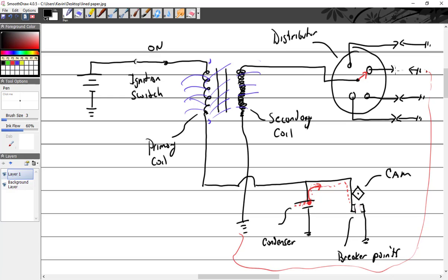However, there are some engines that have staggered timing. That's very critical. One spark plug goes 2 degrees before the other one, and that's to get the flame front, because we'll talk about this later, the flame front, they want it to meet in the middle, and if you light it off from one end, it doesn't. So it's an uneven burn, and then you can get a little vibration from that. So, all right. Do you see how this is going to work?